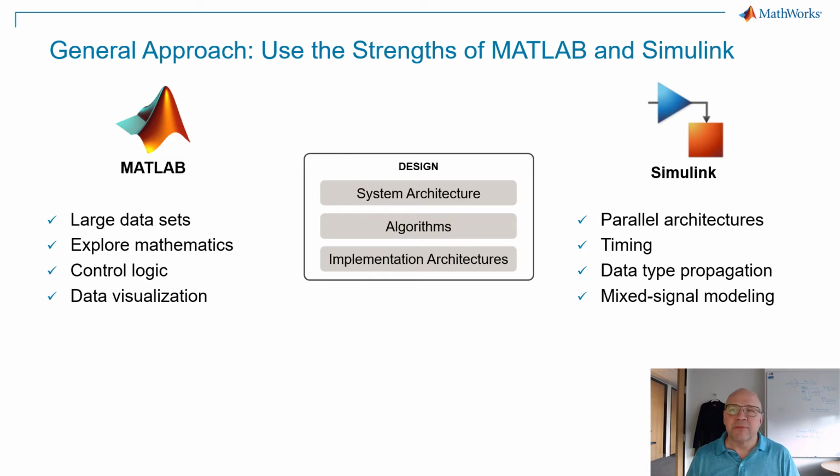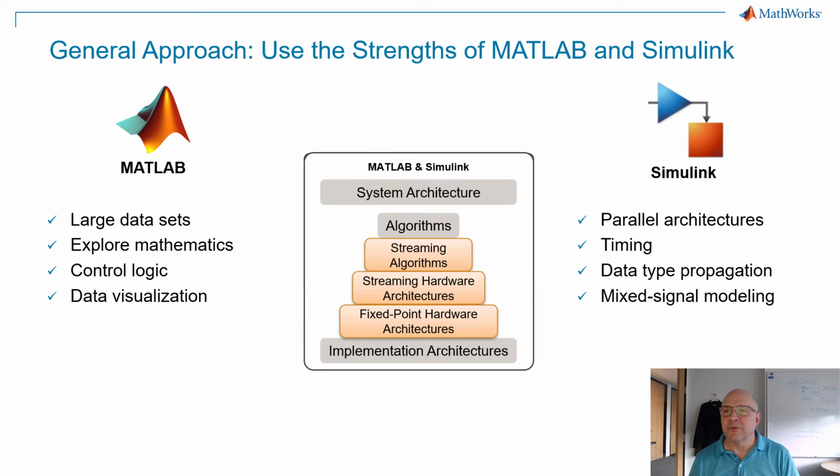Realistically, what we end up finding is customers often blend the two approaches. But whether you're using one or the other or both of these tools, what we're advocating for is a workflow where you start off with a high-level specification in MATLAB or Simulink, and then you refine it. You first reckon with issues of streaming. We'll talk about each of these up ahead. You'll see having to deal with hardware architectures that are different ways of implementing high-level functions, and also the matter of going from floating point, which is how MATLAB and Simulink work by default, to fixed point.